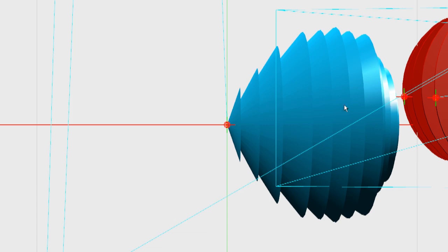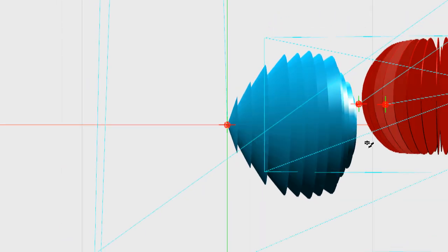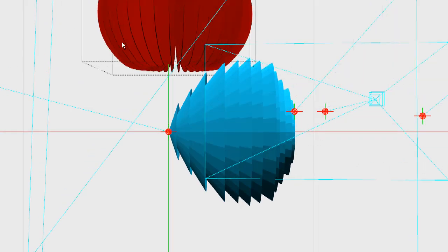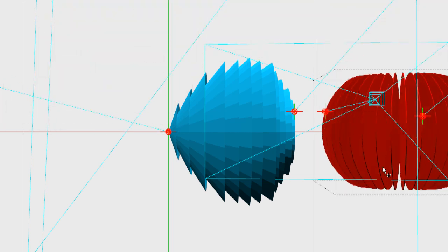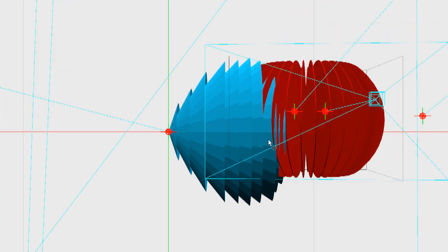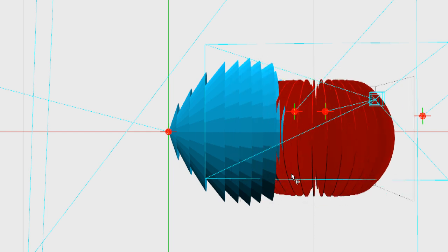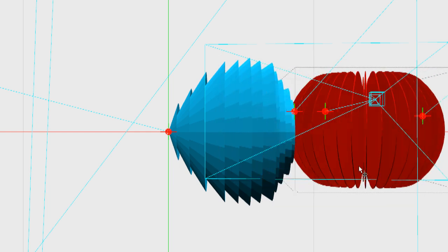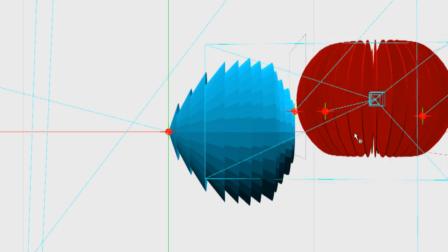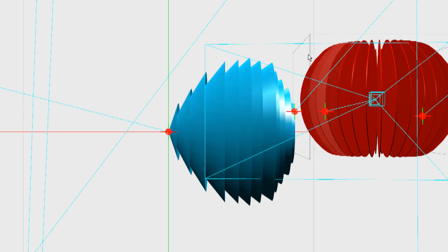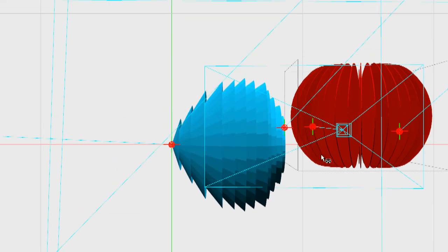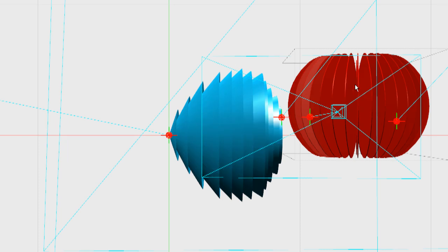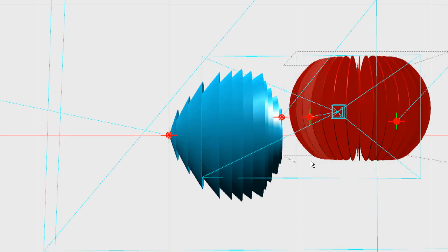It emanates from the face of it. So, there's no good flying behind us or anything. It won't pick you up. But if you're in this vicinity in front of the circularly polarized 8 decibel antenna, you're going to get a rock solid signal no matter where you are around it, despite that 3 dB loss. Because again, if you compare that to the linear differential, that's 26 decibel loss, yeah.